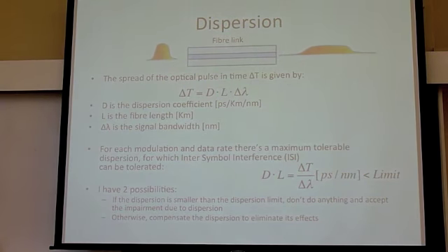Should be okay. Would the power loss due to dispersion be accounted in the margin? No, you have to account for it before the margin, in the loss, because it's something quite deterministic. So it wouldn't be fair. People put it in the margin and then increase the margin by 2 dB.